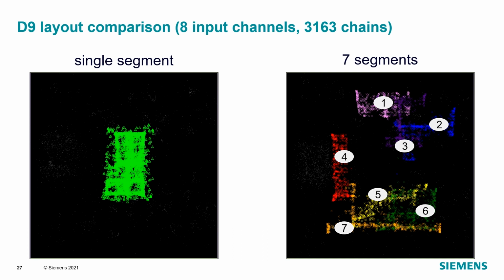An example of layout for design D9 is illustrated in Figure 8, where the locations of EDT segment cells are highlighted in the layout. This design has over 3,000 scan chains, so using 500 scan chains per module, it actually requires 7 segments, each driving at most 500 scan chains.